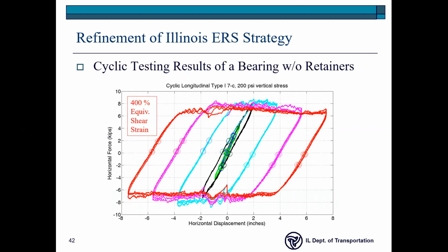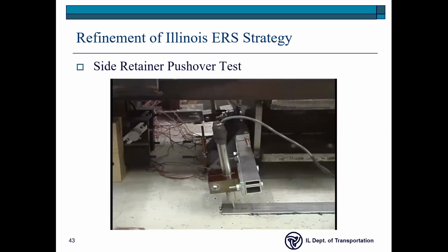And of course, you can see we would get these typical kinds of responses where we measured the back and forth nature. And if you're familiar with earthquake engineering at all, you'll see plots like this a lot of times for columns and various things. And we would typically call plots like this hysteresis loops. But it really helps us characterize the bearings.